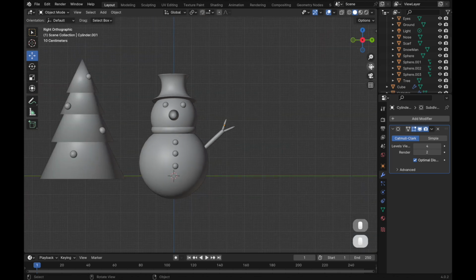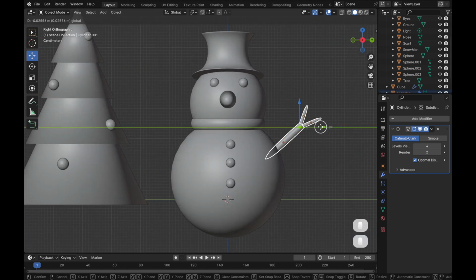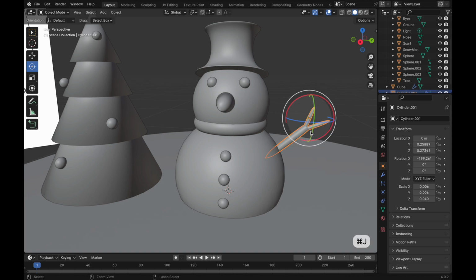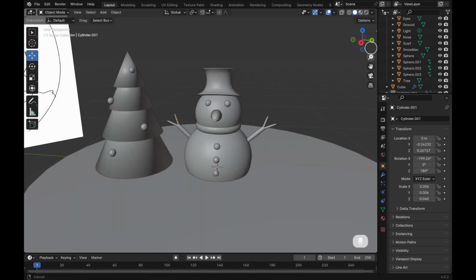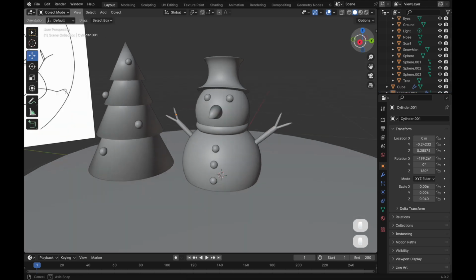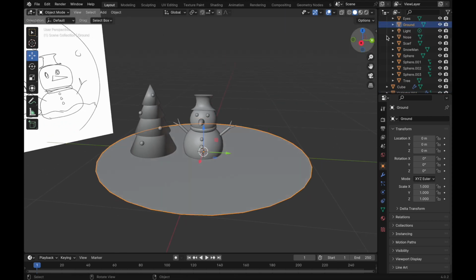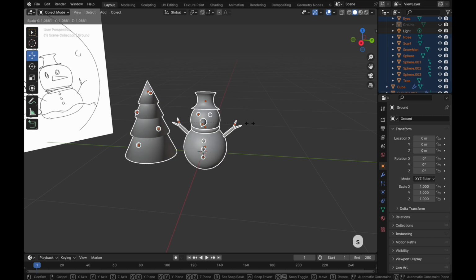After perfectly placing it in the right position, click and select all 3 meshes and press Cmd+J to join them. Then copy and paste, Ctrl+C and Ctrl+V. Go to the rotation section Z-axis and type in 180 degrees. Then use G to grab it and position on the snowman. Check how they look from far. Reposition if needed. We'll also scale them up and position them at the center of the base circle.